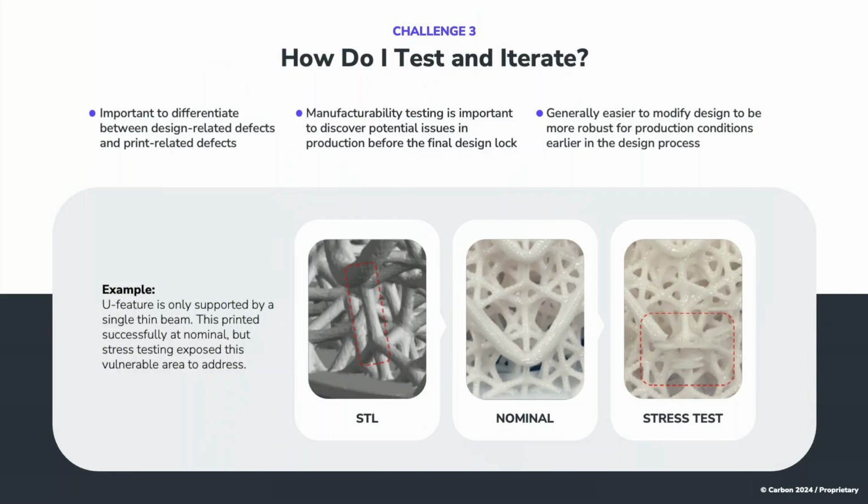And so internally what we do is, once we have a design that we feel confident about, we put it through this manufacturability testing. So I know it's easy to print one thing in a lab. When you're printing 50,000 of them at a facility, you want to make sure the first one and the last one are similar. And that's really hard with elastomeric materials.